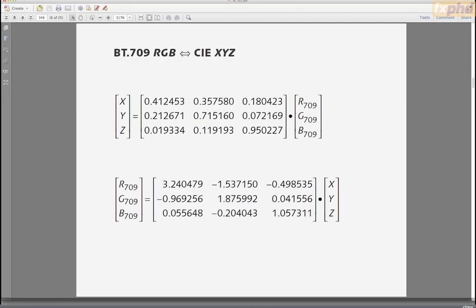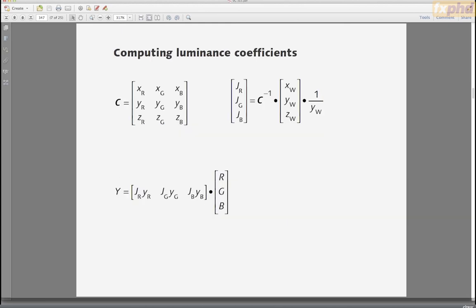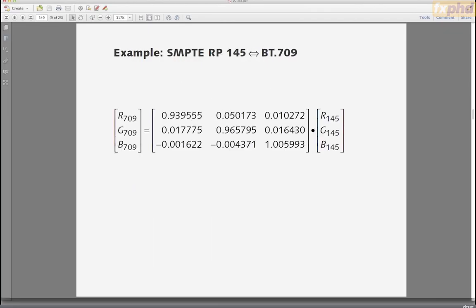And the gamut mapping required to carefully go from one color space to another, like from P3 cinema space to 709 space if you're mastering Blu-ray, that's gamut mapping, and that's complicated. That's more complicated than just a 3x3. And there's math, and my orange book explains all this math of how you convert among different RGB spaces using a 3x3.